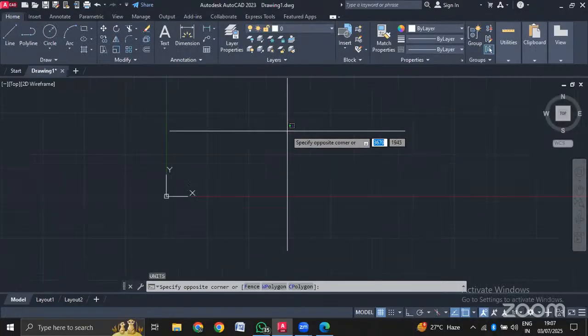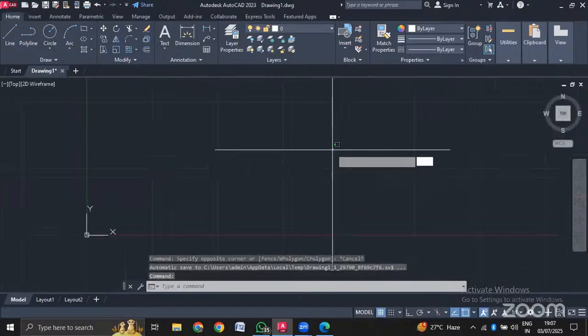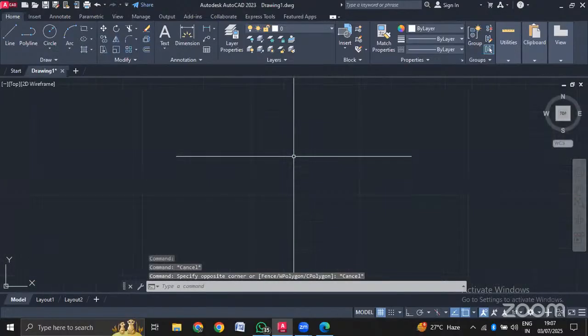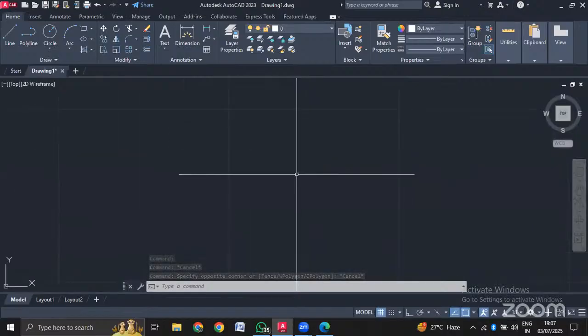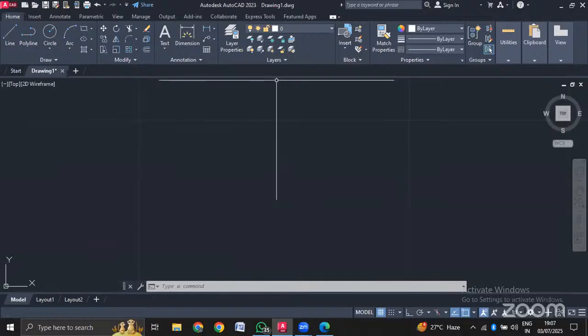So instead of drawing your figures in this completely zoomed out condition, see, whenever you are dealing with AutoCAD, you need to maintain the precision. So for electrical drawings, we generally prefer something called the base grid, or the lowest grid. So you just zoom in, and we'll be going for the base grid. From here onwards we'll be drawing.